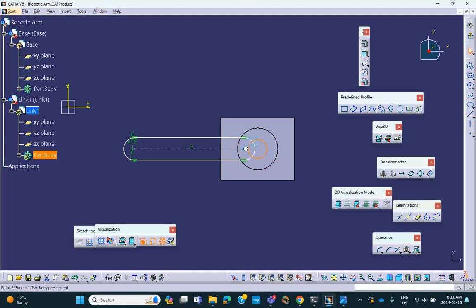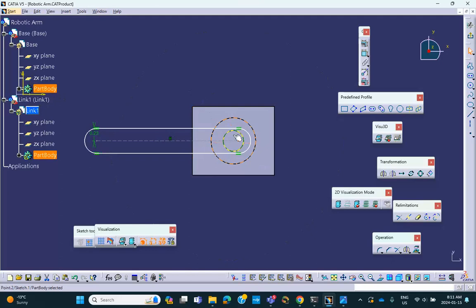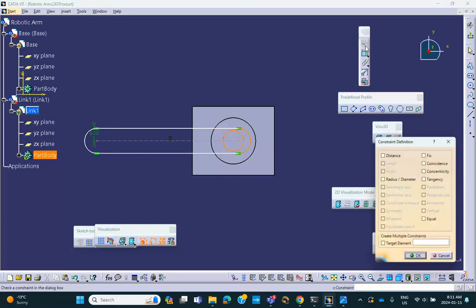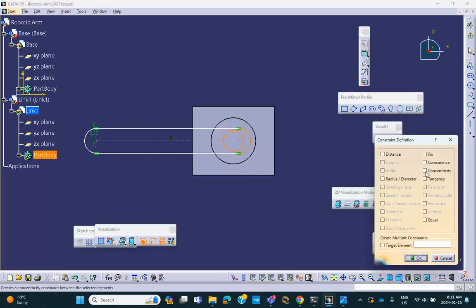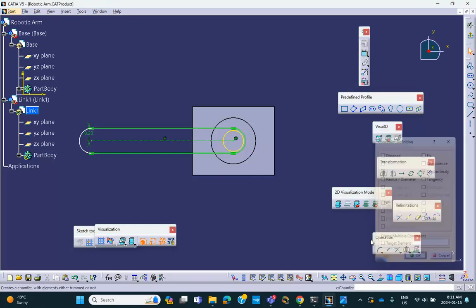Okay, so let me make this, drag it a little bit more. That's going to be link number one, except that I insist on making this concentric with that. There's no reason to do that, but I like it better. Please, when you're writing a test or doing a project, make sure you respect dimension if you're given a constraint. So anyway, I selected these two and I go down here and I say make it concentric. Okay, good.